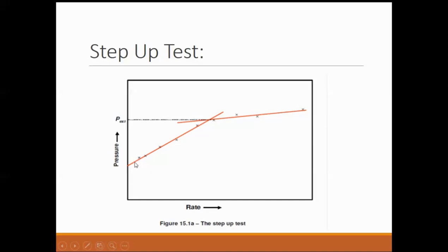Sir, how do we calculate the optimum size of sand particles? Yes, sir. First of all, when you are going to frac a virgin formation, you will first run drawdown tests on it and identify the actual permeability of the natural reservoir.